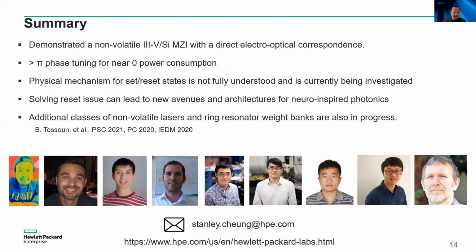In summary, we've demonstrated a non-volatile III-V silicon MZI with a direct electro-optical correspondence. We saw a greater than pi phase tuning for near zero power consumption. The physical mechanism for the set and reset states is not fully understood, and we're currently investigating that. By solving the reset issue, I think that can lead to new avenues and architectures for neuro-inspired photonics. We also have additional classes of non-volatile lasers and ring resonator weight banks, and those are currently in progress by my colleague, Bassem Toussaint.